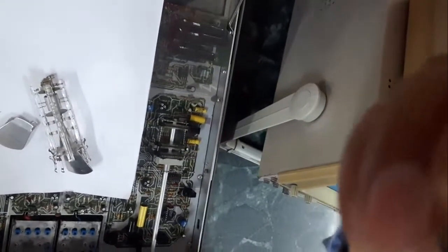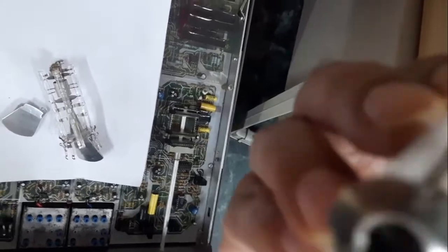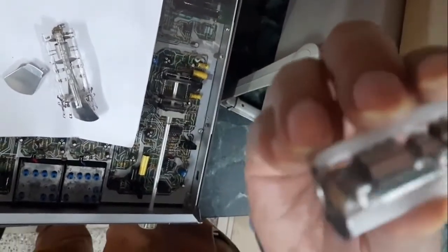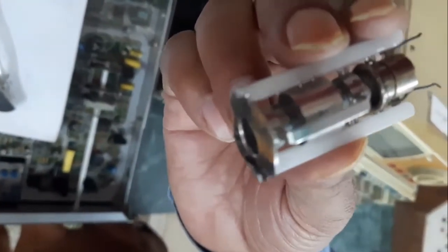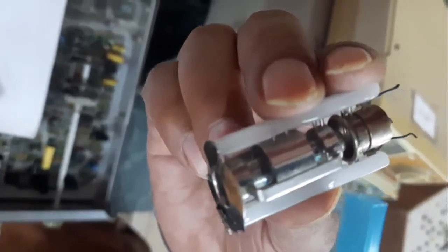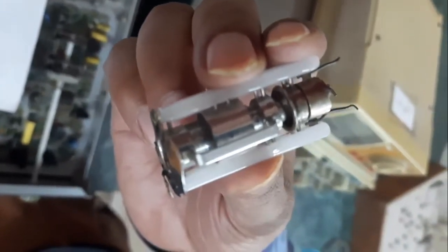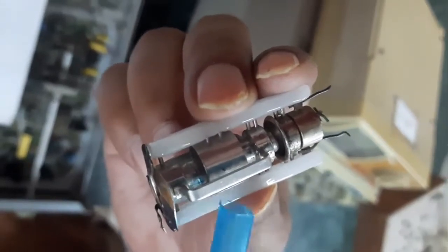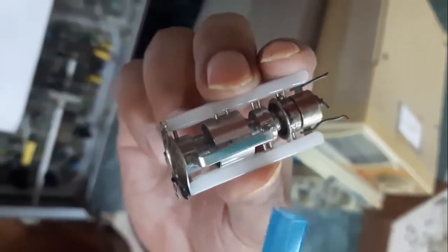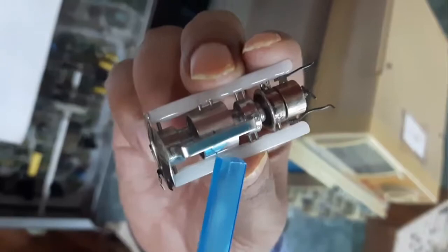The center part of this one is again a hollow cylinder. You are able to watch the hollow cylinder here. This cylinder is the focusing anode. So why is this focusing anode situated at the center? Because the focusing anode is used to focus the emerging electrons from the control grid. When the electron passes through the control grid, its motion is not linear, its motion is not controlled, so that's why the focusing anode is used here. That is the cylinder here, which is kept at 500 volt.